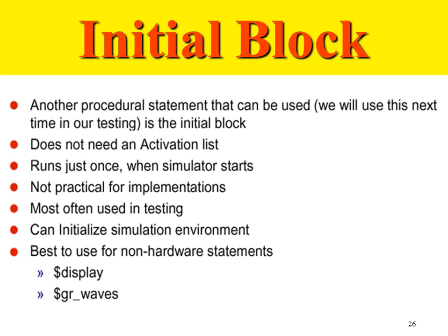From memory, after the reset, like after the vector table initial, how does that work? When you power up the board, and you don't have to apply reset for that, it shows you that. Some LEDs will glow, some message will be displayed. How does that work? After a certain time in the vector table, it goes to the main of the program and starts executing from there. The program counter. Main will happen later on if you're comparing it to an embedded program. But on reset, that's on power up, basically.